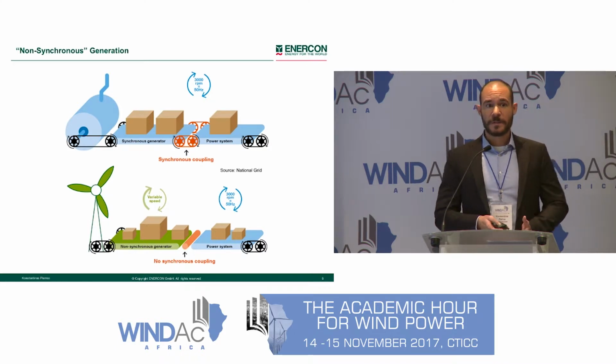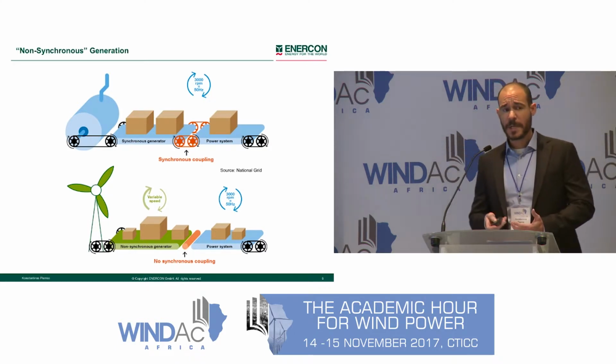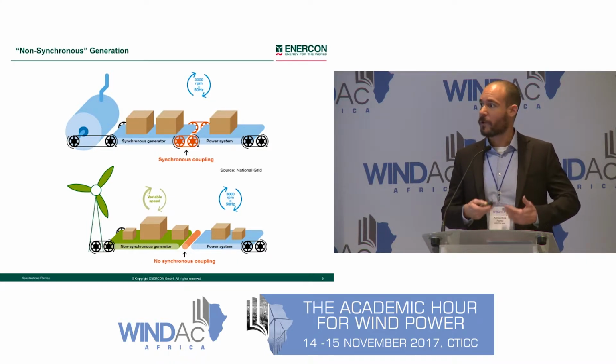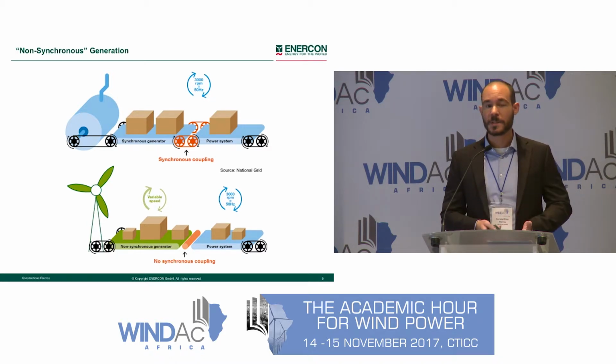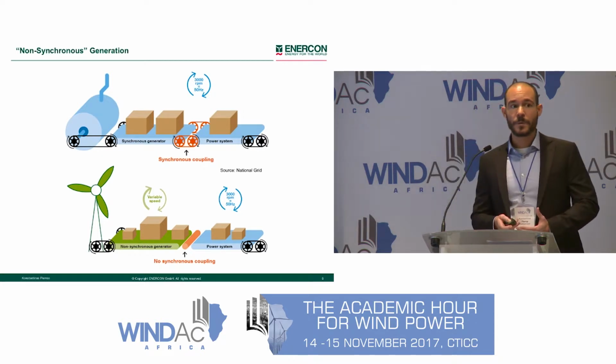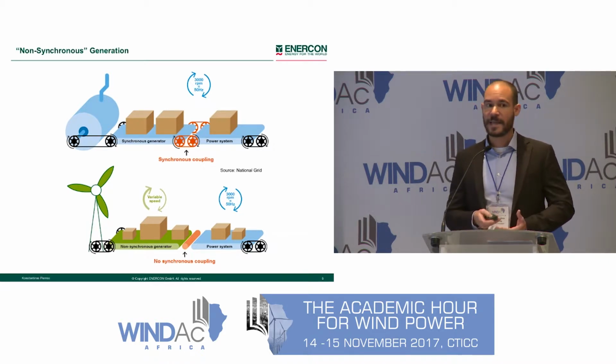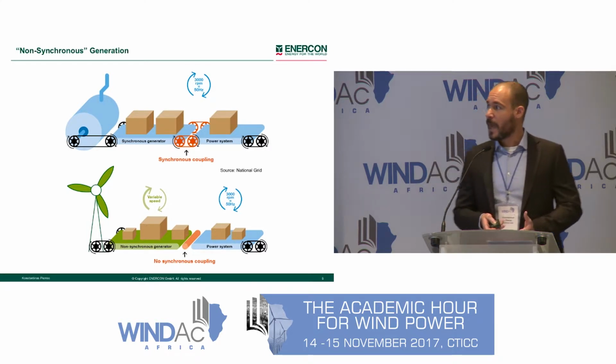For this reason, several system operators have started looking into requiring wind power plants to provide a form of synthetic inertial response for under-frequency events. By doing so, they aim to increase the maximum allowable penetration level and facilitate the more efficient and economical use of wind energy.